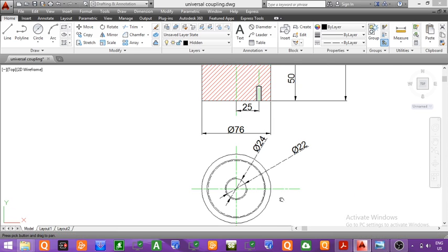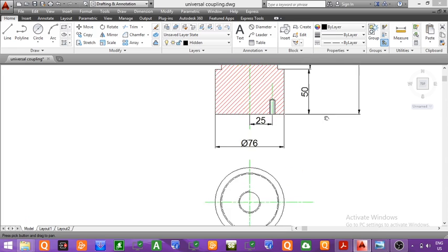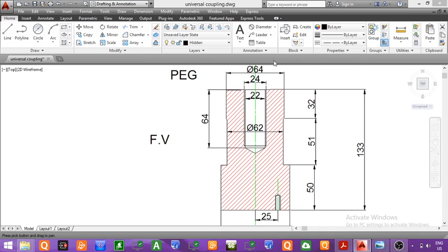Now in the next step, we will draw the top view of the hole which is provided for inserting the cap screw. Now this hole along with the threading will not be visible from the top since it lies at the bottom of the locating peg. Since this hole in which threading has been performed lies at the bottom of the locating peg, if we observe the peg from the top view, this hole will not be visible, so they will be drawn as hidden circles.